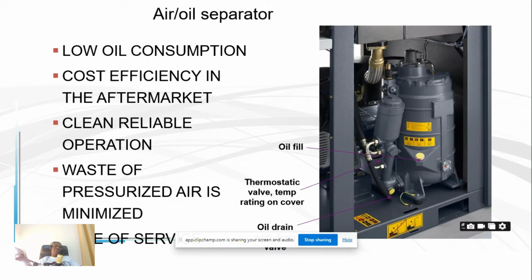For example, let me use textile again. You're making textile and you're using an oil injected compressor. With oil carryover, you see the textile will get contaminated. Of course, for textile, it shouldn't be oil injected, it should be oil free. But some customers sometimes add filtration, they use oil injected because it's quite cheaper for them.